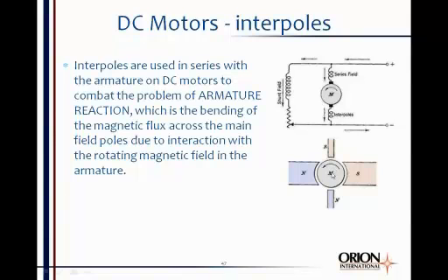If the motor's heavily loaded, then it's going to have more current flow in the armature, and you're going to have more armature reaction occur. So what that means is the neutral plane shifts around all over the place, and then that causes you not to commutate in the neutral plane. Well, if you don't commutate in the neutral plane, you have a lot of arcing and sparking that takes place at the brushes and the commutator segments. It destroys the commutator segments and burns up the brushes, so not a good thing.